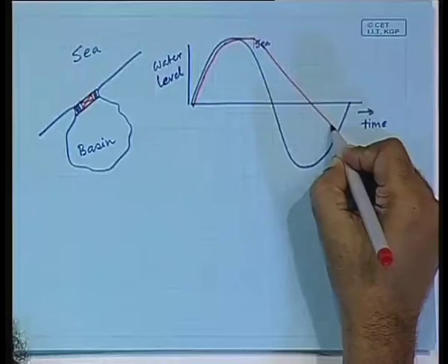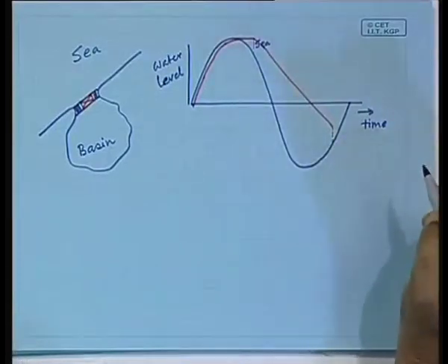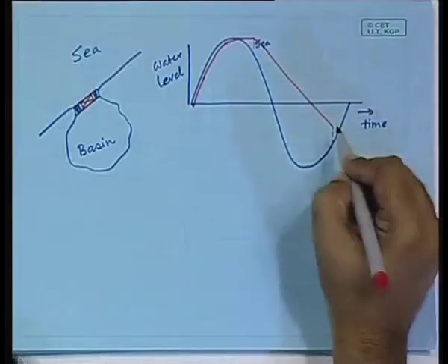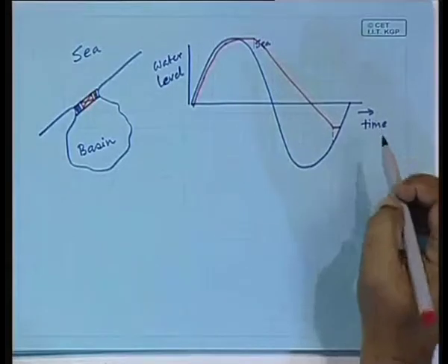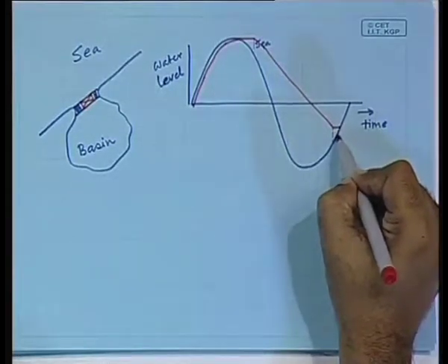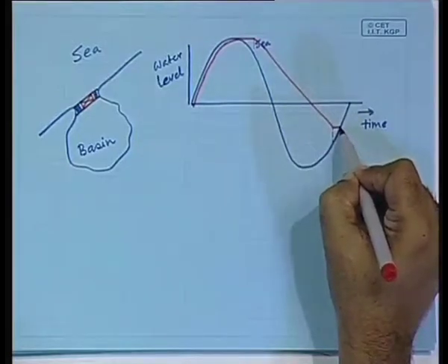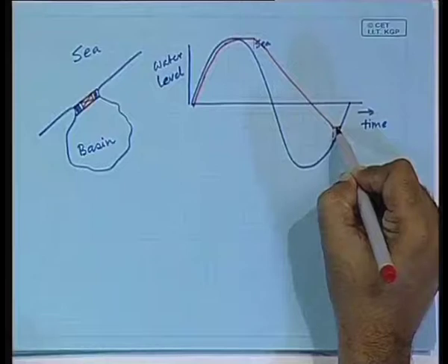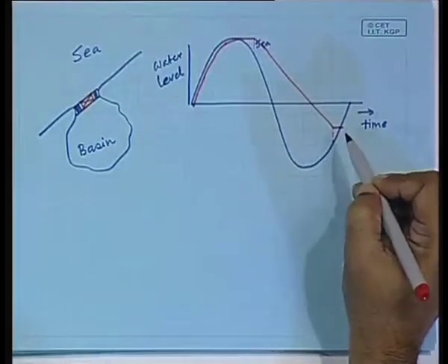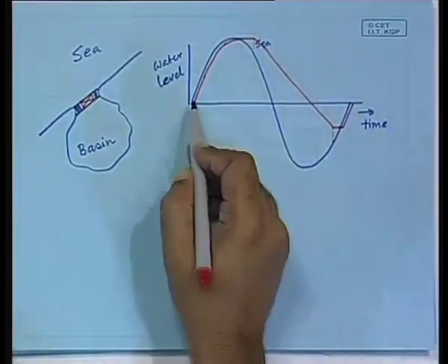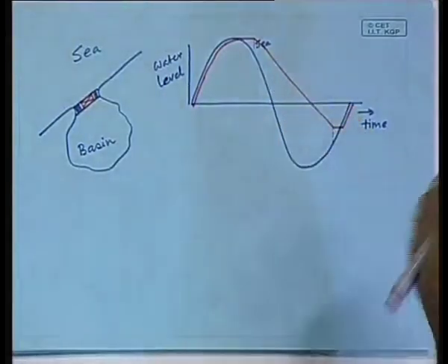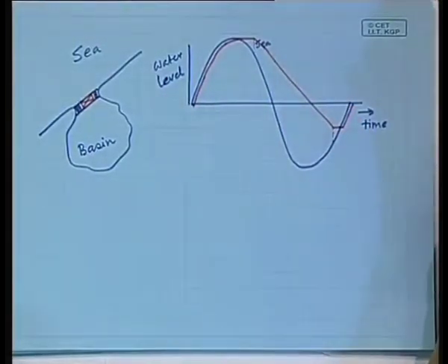And after some time again the head becomes insufficient to generate electricity. Then again the sluice gate is closed. And then after the two levels become the same, the turbine was closed, the sluice gate is also closed. At this time the sluice gate is open, not the turbine, and then it follows the same route as here. That cycle repeats itself. Is that understood now?